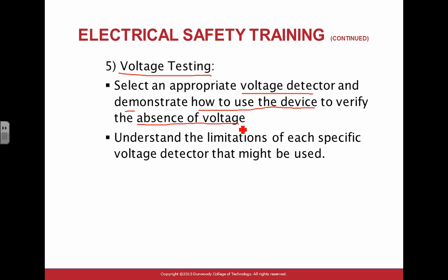There are a lot of VFDs with transients going up and down in the system that can shoot the voltage up to 2000 volts and bring it back. That transient goes into your system, could go right here and short this one, and make a ball of fire in your hand. So that's what you're going to be rating of the equipment in a second.